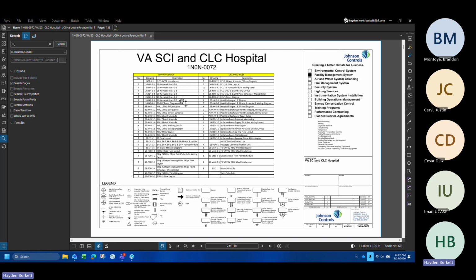This covers the rough outline of all of the equipment that we have on site, and which Johnson Controls network engine these devices are going to. We have an example of an S&E panel diagram. We go over essentially the air handler units, what devices they have on them, and the sequence of operations.